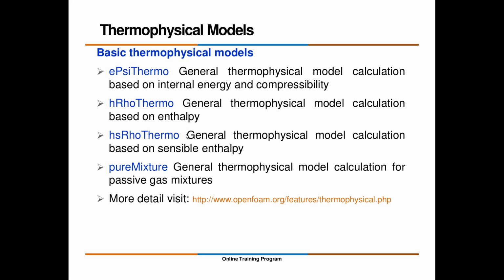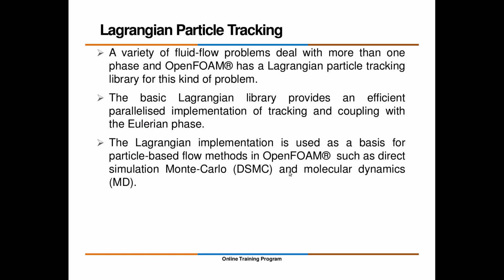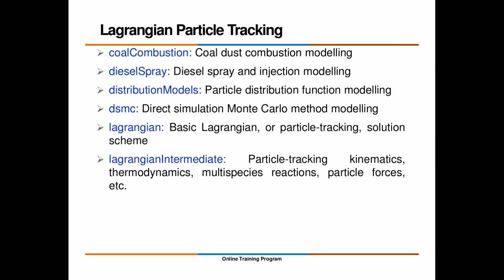But sometimes, let's say you want to change this modeling style. Right now we are saying temperature only depends on certain things, but later on you apply some electromagnetic force and temperature also depends on electromagnetic force, then you have to change certain libraries, okay. Lagrangian particle tracking is available with OpenFOAM, okay. So Lagrangian theory based libraries were created, and you can adopt that library and look at Lagrangian particle tracking in different versions of the applications, okay.